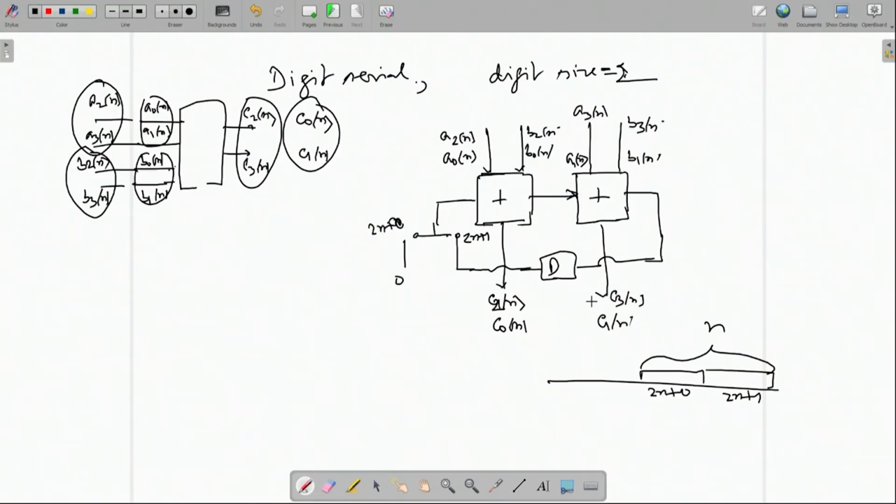So, we will show that from our bit serial structure, if we had unfolded it by 2, we would have got this. If we had unfolded by 4, we would have got the original one. This we will discuss next time, but then we have to first see how to handle a switch. That is, if there is an edge between two nodes U and V, forget about delay. Earlier, if I had U and V with a line directly connecting, it means the signal is always going from here to here at all clocks. But whenever I switch, it means at certain clocks the switch is closed and the signal is going, at certain other clocks it is open, it is not going. So, it is a discontinuous kind of thing, sometimes working, sometimes not.